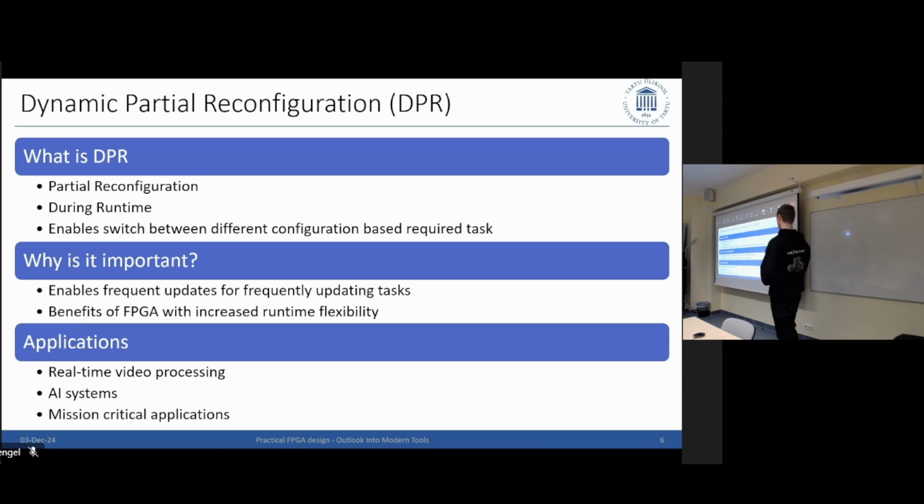Then there's a technology which I find quite fascinating, especially in the space domain, that changes a lot of things. It's dynamic partial reconfiguration, or reconfiguration at all in the space domain. In the past, and especially when there were very well-defined, highly reliable projects or space probes, we never reconfigured our FPGA. We used FPGAs which you programmed once, and that's still the thing. You program your FPGA once and that's it. You never reconfigure it, you never change it. And that's how it works.